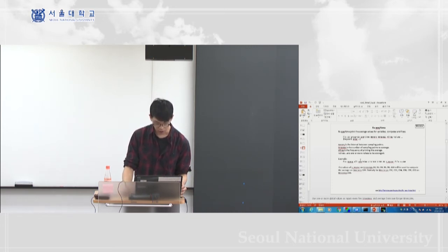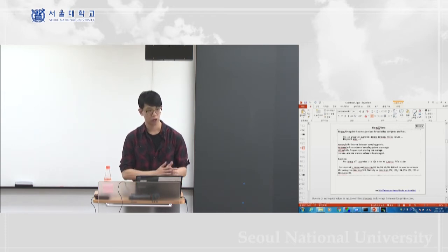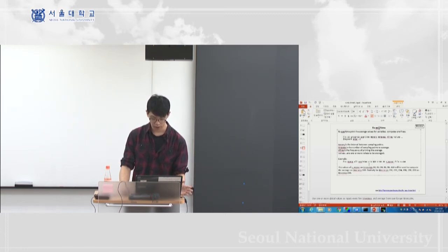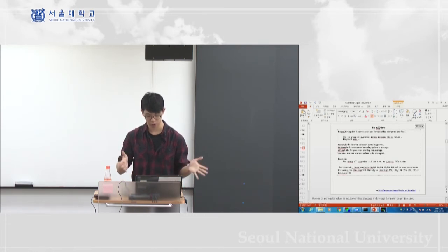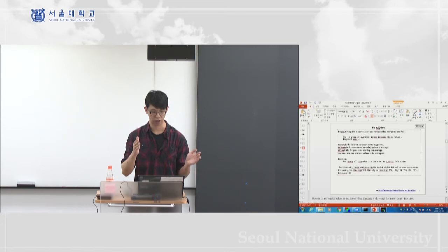So here you have to give 3 numbers. The third one is Nfreq, how frequently you want it to print out the certain variable. So if you write 100 here, then it's gonna give you the value every 100 steps. The second number is how many variables you want it to average for you.